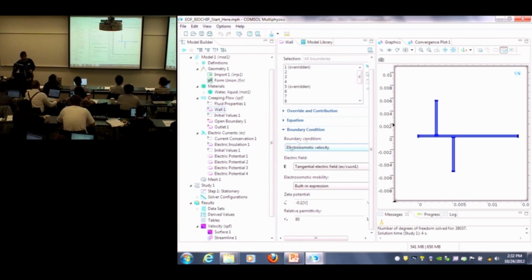So the overall idea was to introduce this boundary condition, which is very handy, especially for the microfluidics community. If you have pressure-driven flow as well as electroosmotic flow, you can mix the 2 things together. And something similar will be worked on in a hands-on example, like an electroosmotic micromixer. And then we will also add mass transfer to see how 2 species will mix together.